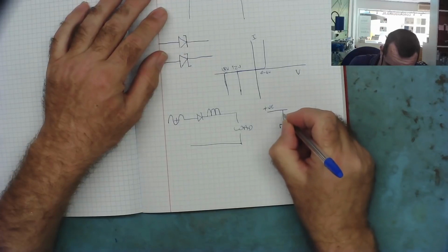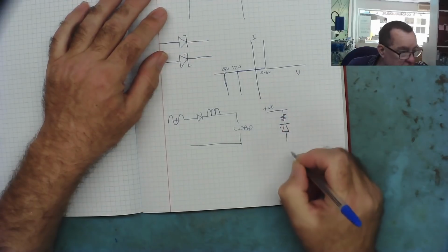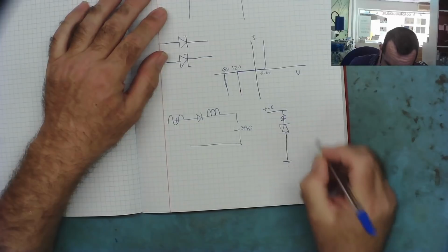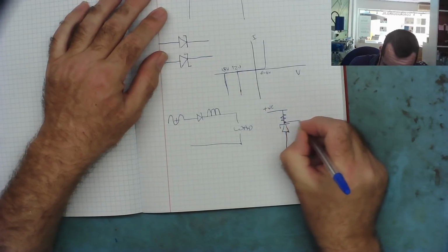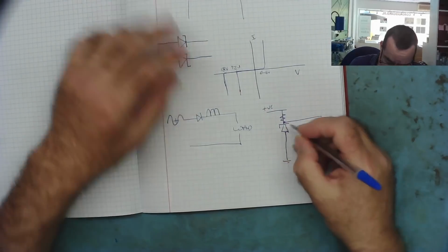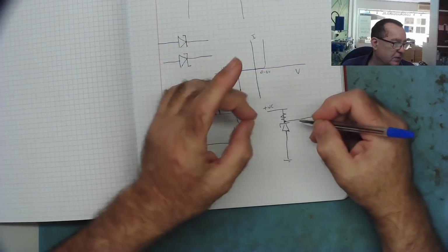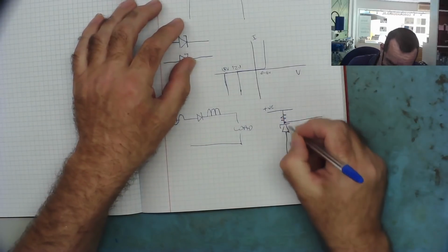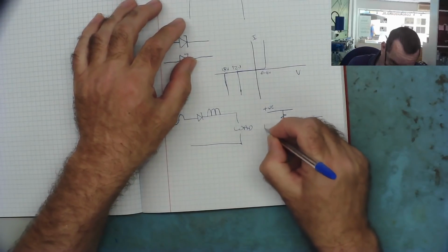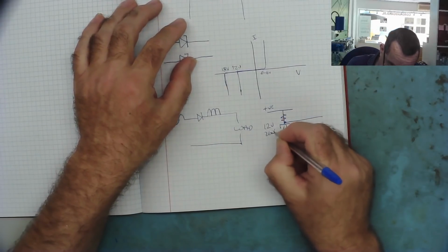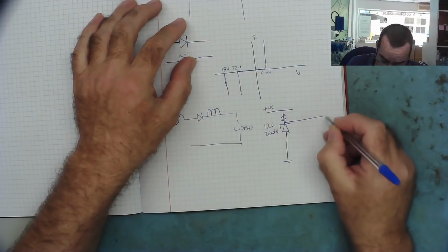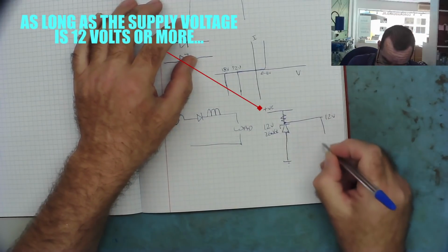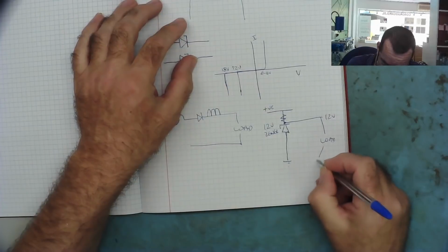It will have a resistor to limit the current. We'll put the resistor in here, and typically it will go to ground. And at this point here now is a voltage that is regulated by the diode. So if this is, for example, a 12 volt Zener, the voltage here will always be 12 volts if you measure it. This can be your load to ground.